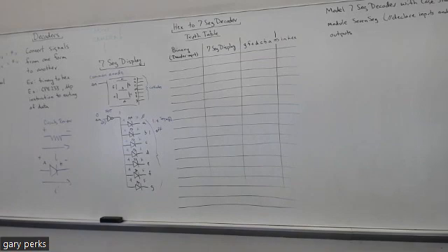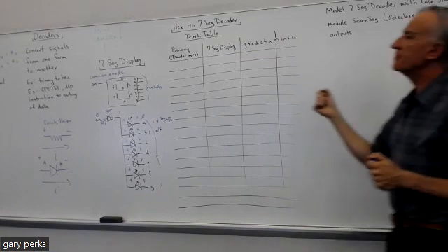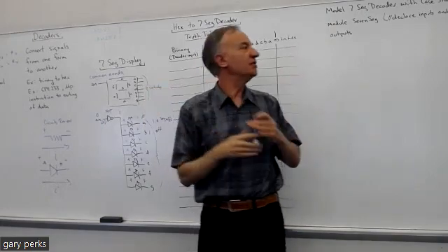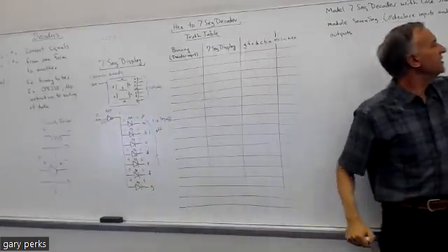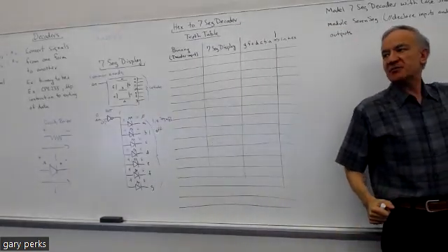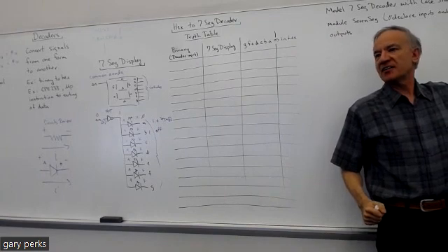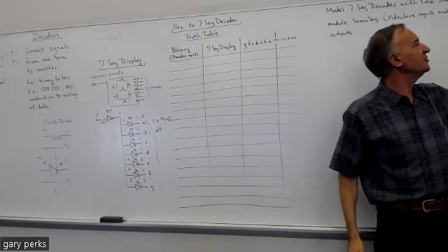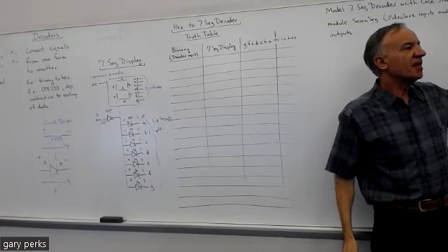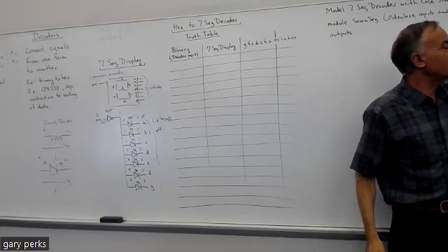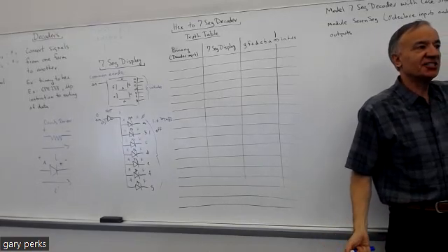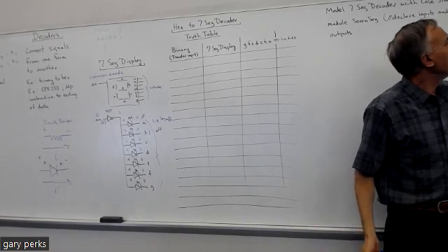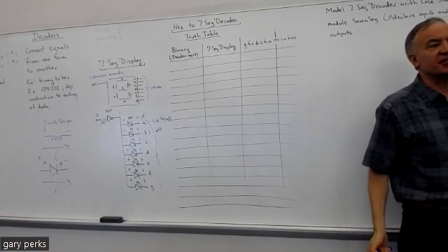This decoder has a 4-bit input, because we're taking the 4 bits coming from the sum output of your RCA. Remember the RCA from lab 2? That's where the result of the addition is, and that's what we're going to feed into the decoder.